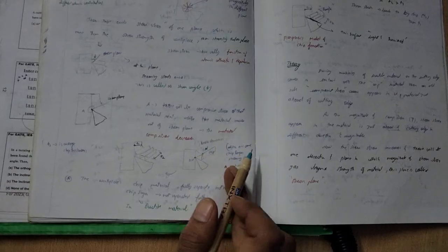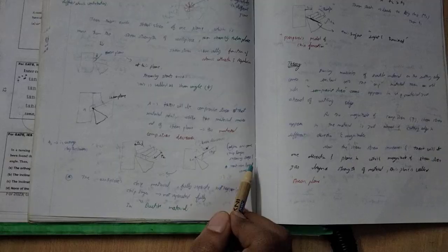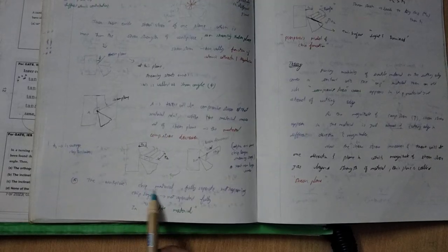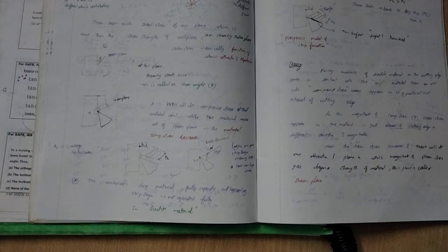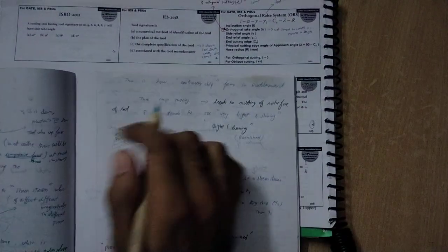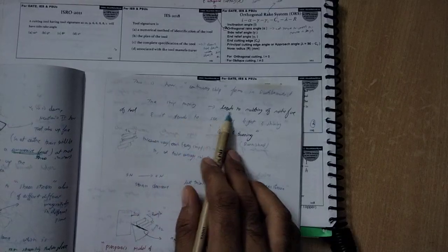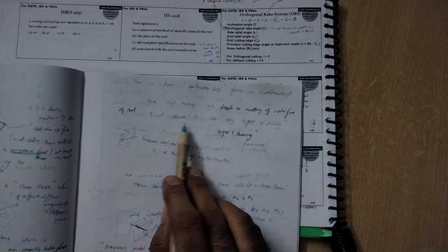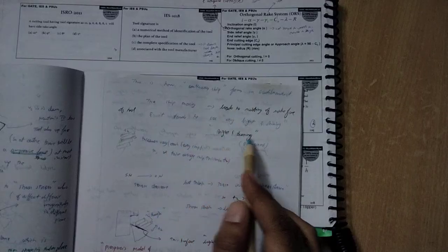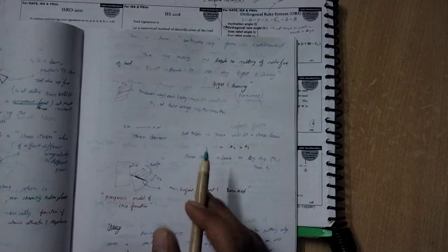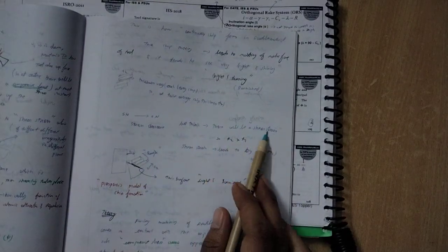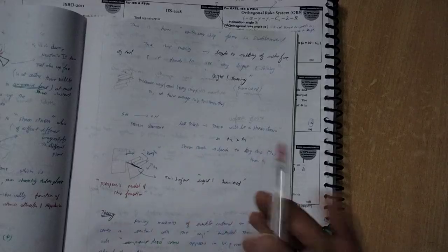After coming into the chip layer, shearing stops, and then the next layer continues. The chip material does not fully separate from the workpiece in ductile material. This is how continuous chips form in a ductile material. The chip moving leads to rubbing on the rake face, and definitely it leads to burning, so the surface will be very shiny. There will also be shear strain and shear stress.